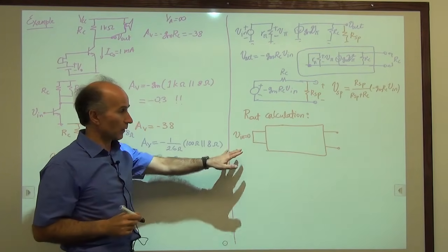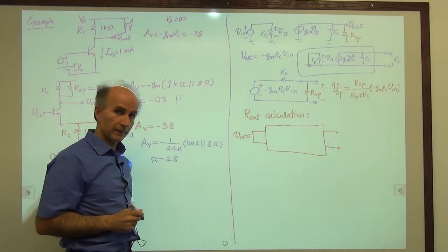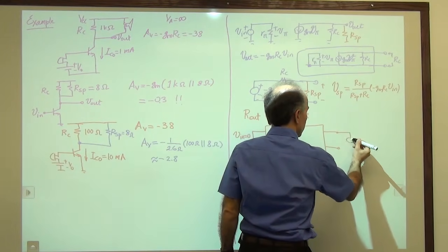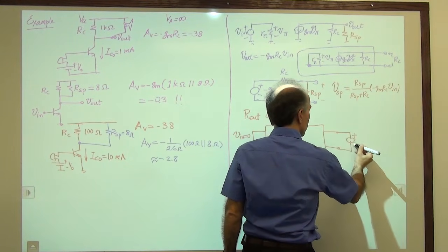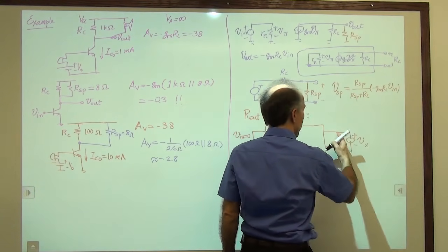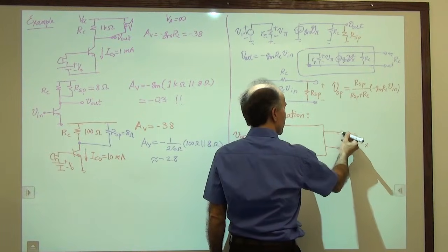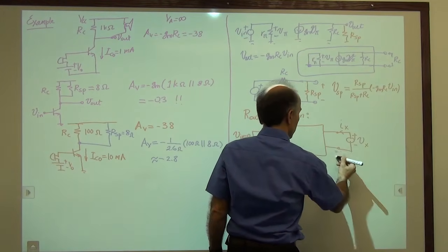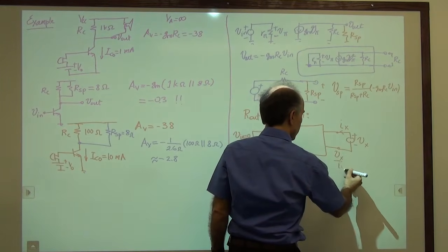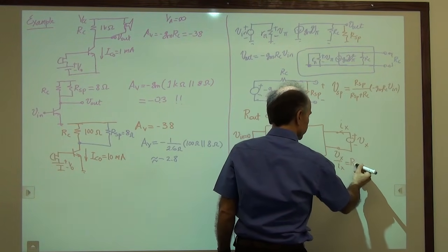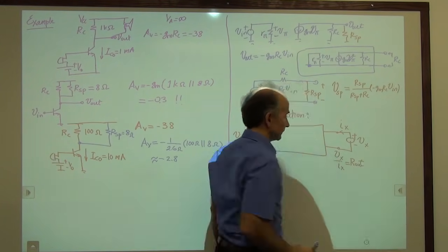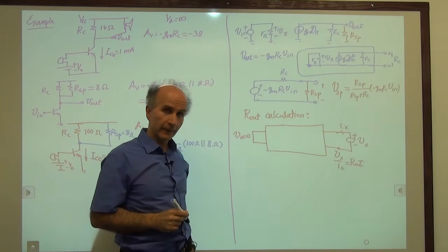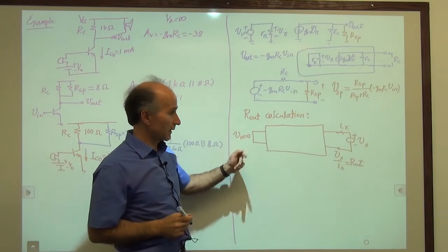All right, these are of course all small signal calculations. And then we go ahead, and if you want to do it formally, we apply a voltage source, Vx, to the output nodes and measure the resulting current. And we say Vx over Ix is R out. So that is the output impedance, output resistance of the circuit when it's calculated under these conditions.